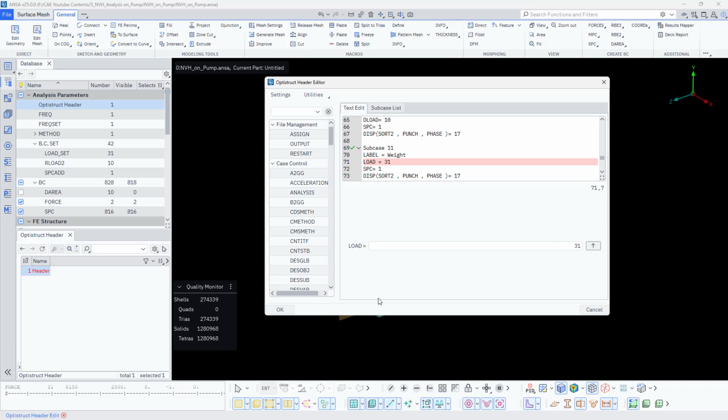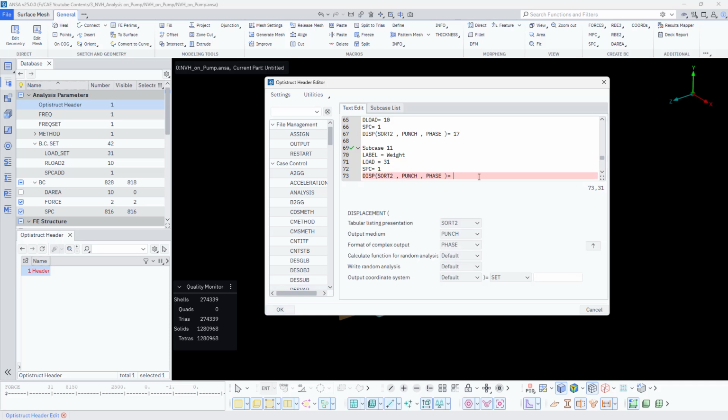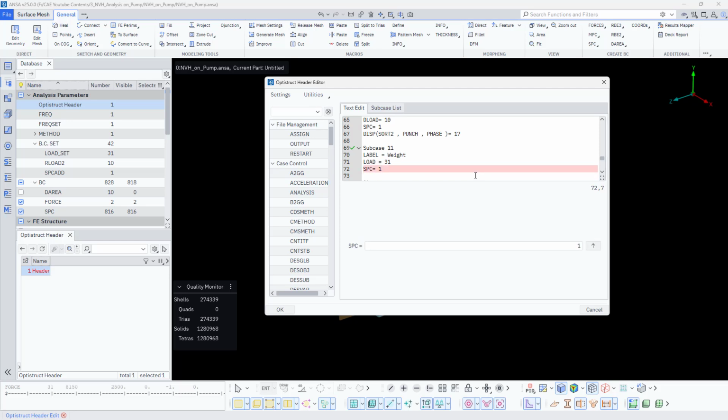Yeah. So now you need to refine the output, like remove the PCH curve. It is not needed. I need to extract the displacement and stress for this particular subcase, right? You can do the same here. You can just simply type in Hyperview. You can simply go and select the output formats for each and every subcase, and you can even define it globally here also and there also. But here, the only thing is you need to manually define it.